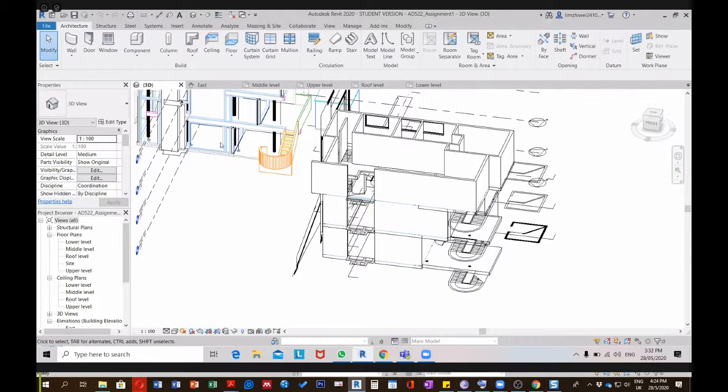The only difference you can say, maybe this one defines slope, because roof can contain slope and it can be flat. Now if you see our product, it's flat, it has no slope. We go to and see our 3D AutoCAD 3D, it has no slope here. So basically we can do it even using floor, but it's better to use the specific function to model it. So I will go back to my roof level, and I will just follow, because I can see it's very simple. I will just follow this shape.